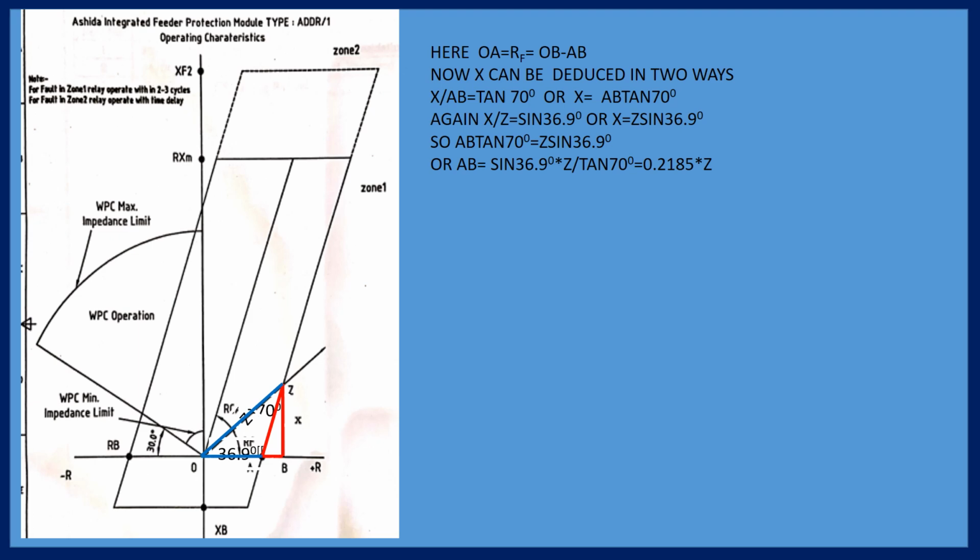Not in parallel. So the connection will be in series. Both the secondary coils will be connected in series. But if you see in the field, S1 is connected after the relay with the S2, but that is in the electromechanical relay. That problem is worked out in the microprocessor relay. Simply you put the secondary to the relay. So that is not required. But if you want to know the basics, then you have to think about 132 kV.